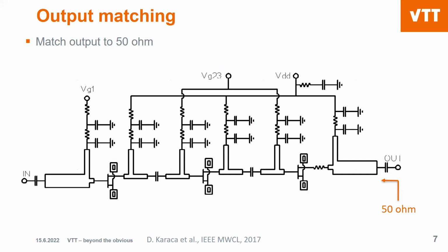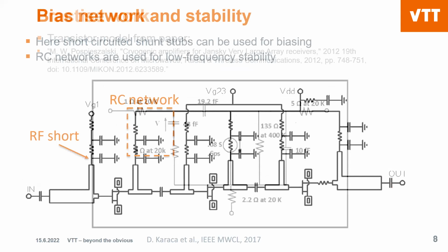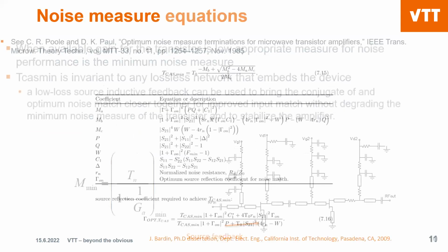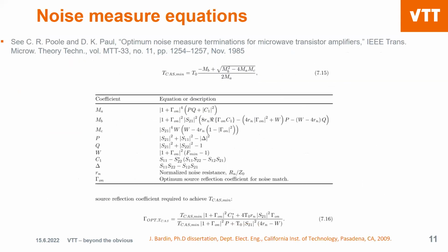Yes, this will go down if you cool it. So that was a cooled transistor. Actually, that model is used to design the LNAs that were in the Green Bank observatory. So that is the model, not this one, the one that was in the first slide. Yes, so that is from that transistor used to design the amplifier.